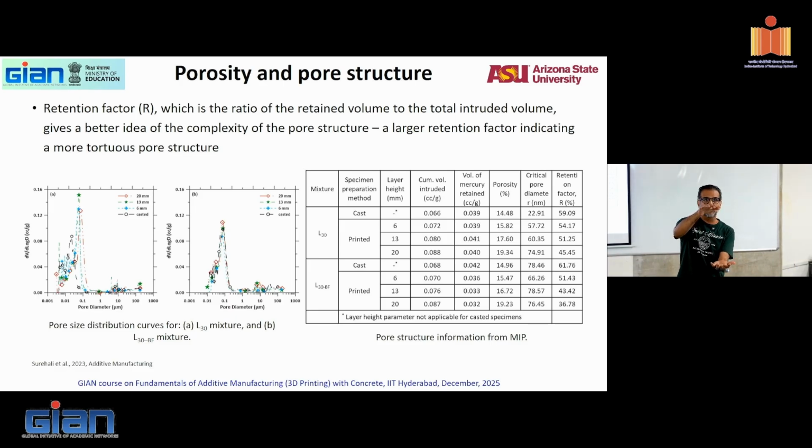But if I enclose it in a sleeve, all of you have done that triaxial test on soil, you enclose the soil in a sleeve and apply pressure from all three directions, right? Now you can measure its capacity. Of course, you will get two different stresses, your axial stress and the lateral or dilatant pressure. Remember all of that? Same idea: the piece of concrete is submerged by mercury on all sides, and mercury is squeezing into it from all sides. Therefore, you don't crush it, you squeeze mercury in under a triaxial state of stress.